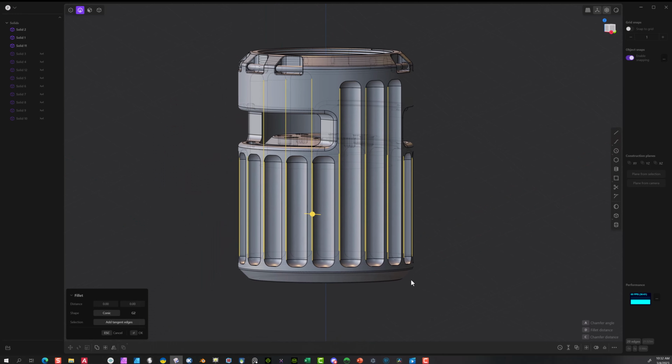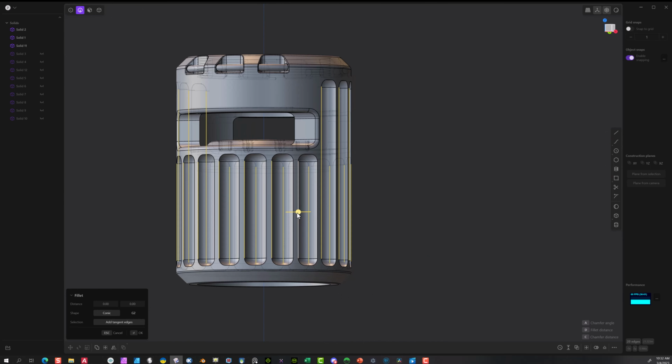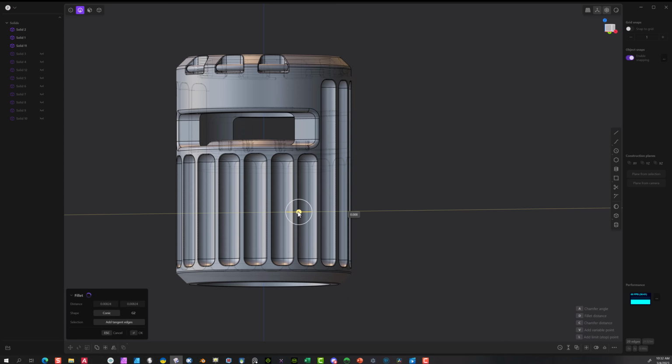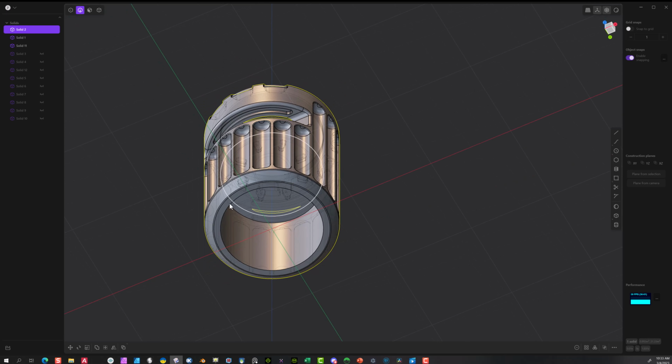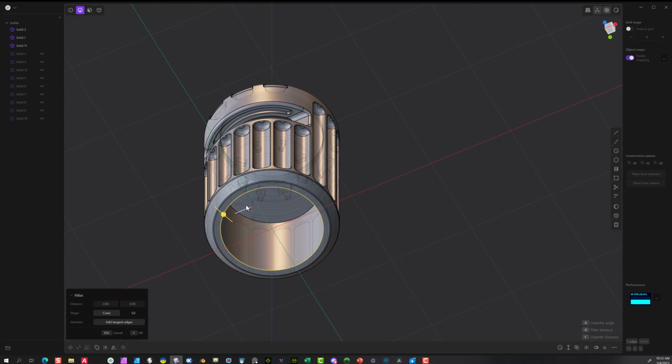Now we can go in and make a little bit of a radius to those so it's nice and smooth. Say OK. And another thing you can do is add the actual pipe extending out of this, or the tube, if you want to. I'm going to say OK.